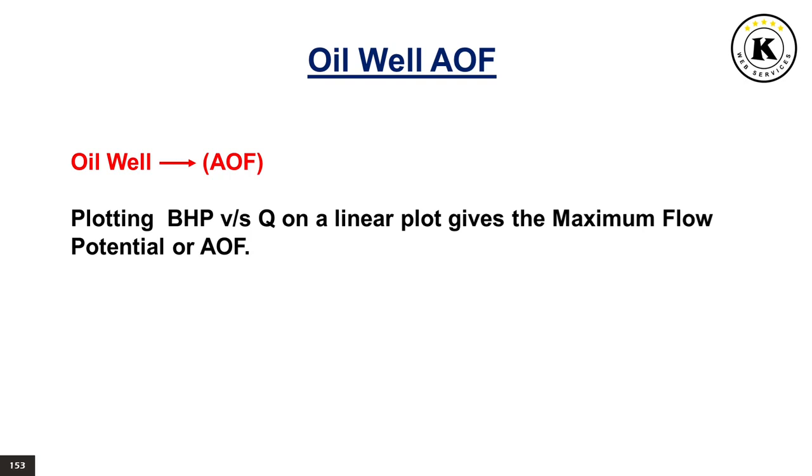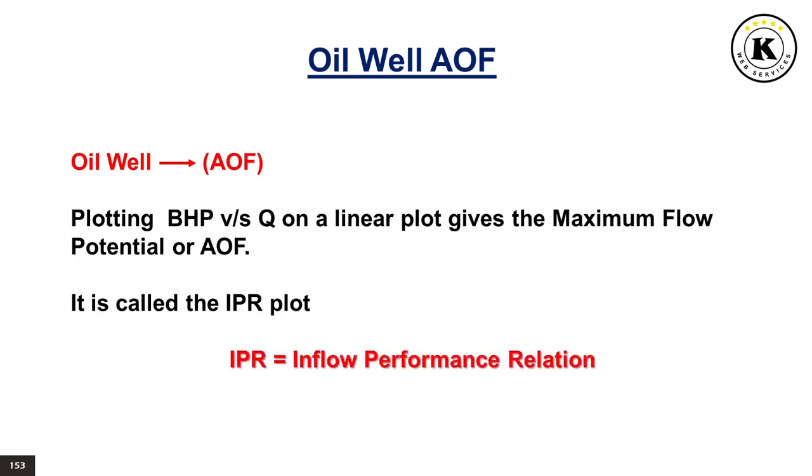Oil well, AOF. In the case of an oil well, the maximum flow potential, or absolute open flow, AOF, is obtained by plotting the bottom hole flowing pressure versus the production rate on a linear plot. This plot is called the inflow performance relation, or IPR plot.